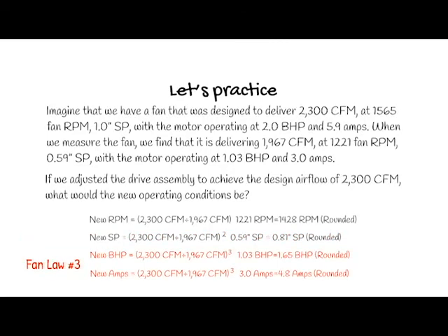Brake horsepower and amps utilize fan law 3. For fan law 3, we use 2300 divided by 1967 cubed. We multiply that by brake horsepower of 1.03, which would give us 1.65, or by the amps of 3.0, which would give us a new amp draw of 4.8.